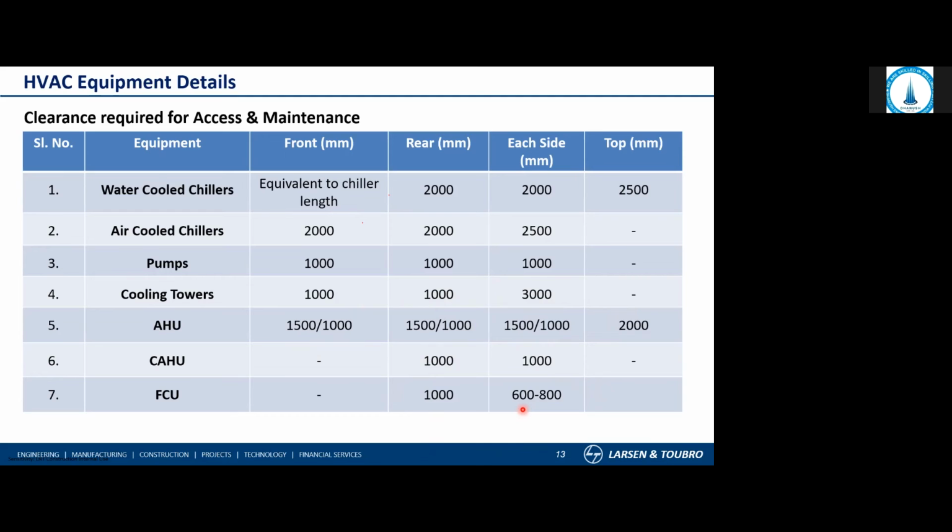Similarly, ceiling suspended AHUs and FCUs also require access for filter cleaning at the back and valve accessibility for maintenance, between the equipment or from the wall and the equipment.